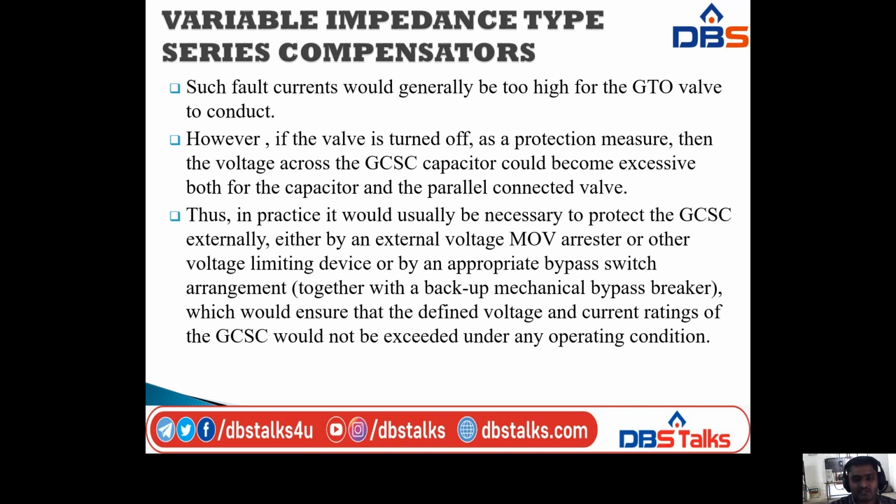However, if the valve is turned off as a protection measure, then the voltage across the GCSC capacitor could become excessive both for the capacitor and the parallel connected valve. Thus in practice, it would usually be necessary to protect the GCSC externally, either by an external MOV arrestor or voltage limiting device, or by an appropriate bypass switch arrangement, which would ensure that the defined voltage and current ratings of the GCSC would not be exceeded under any operating condition.